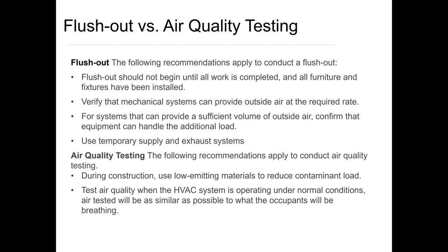For air quality testing, this is a little bit different, but it also is a good representation of what's going on, what types of contaminants you have in your air. And this is performed during your construction. Backing up, during construction, you want to use low emitting materials to reduce contaminant load. That's just across the board. For LEED best practices, the more low emitting materials you can source, the better.